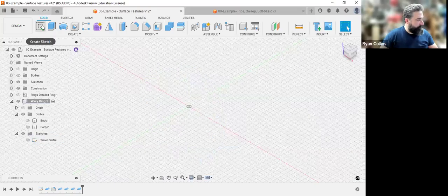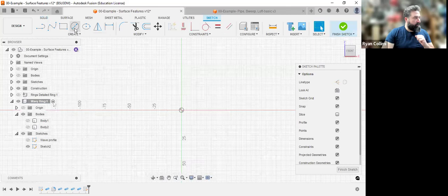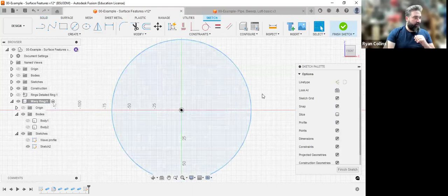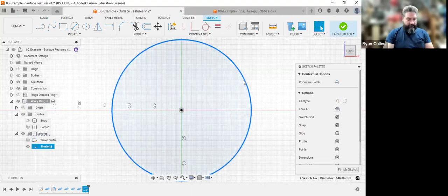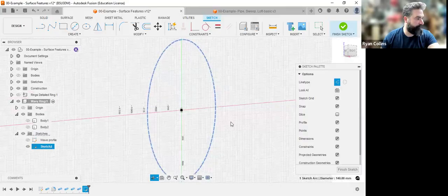So far, what we've done, I'll just create a sketch and circle. Now, this is just going to be a reference point. Since this is just going to be a reference point, meaning this is how big I want the circle, I'm going to turn this into a construction line. So here in the toolbox, or just press X. Just changes that to a dotted line.